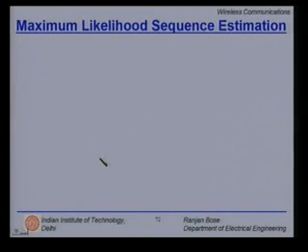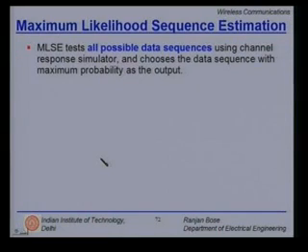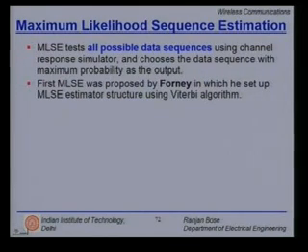Now, let us talk about the next one, maximum likelihood sequence estimation. The MLSE tests all possible data sequences using a channel response simulator and chooses the data sequence with the maximum probability as the output. It was first proposed by Forney way back in '78, in which he set up the MLSE estimator structure using the Viterbi algorithm.